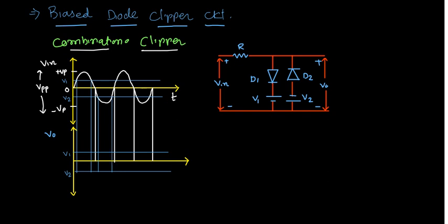So over here, for the positive half cycle, what will happen? When the positive half cycle is there, here will be 0 and over here also 0. Diode D1 already has the V1 supply at its N terminal, and this is the P terminal. So at that time D1 will be reverse biased. And what will happen to D2? Check.